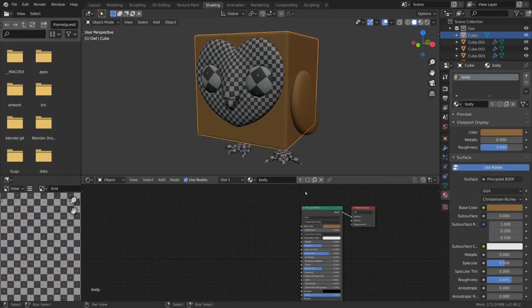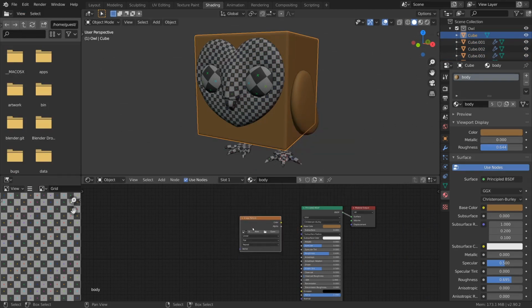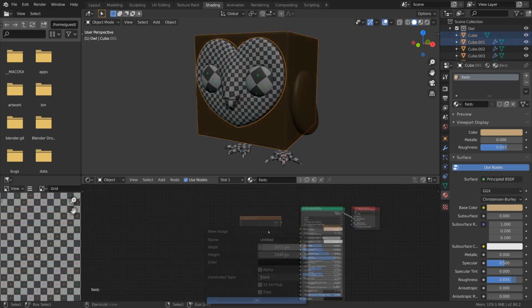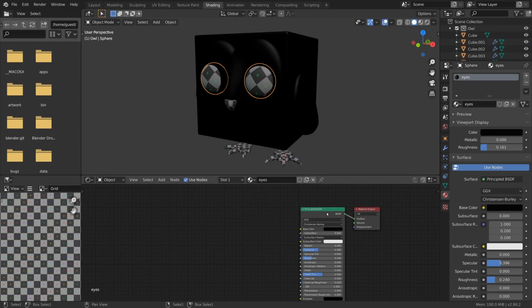To finish off the materials, we can add some procedural textures like shown in the fundamentals, or we can just paint on the model instead. You can then replace the grid texture that we made with a new blank texture, which can then be used to continue painting on. Just make sure it's plugged into the base color so you can see it in the material preview mode.